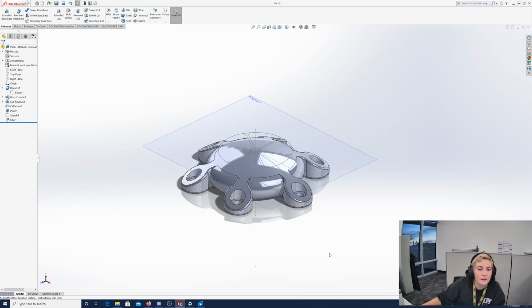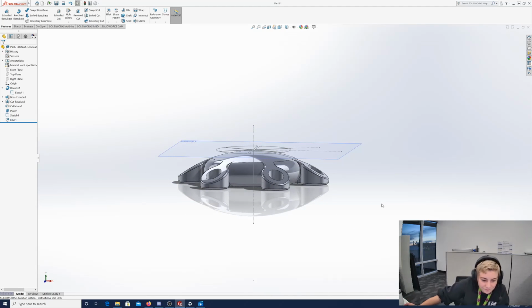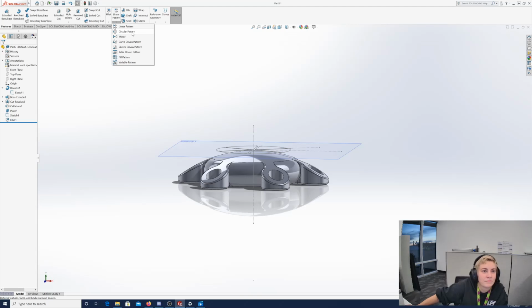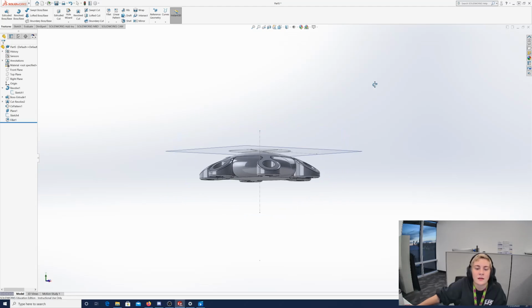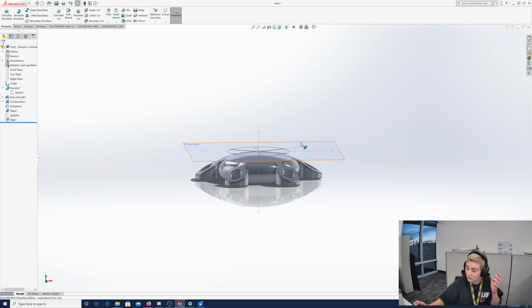So this is basically again how to do circular patterns in your sketches and the circular pattern feature, which is here under linear pattern, you can do a circular pattern. So the key takeaways here, I guess, are in order to make a circular pattern, first you have to have a feature that you want to revolve around an axis, and then you have to have an axis to revolve it around.